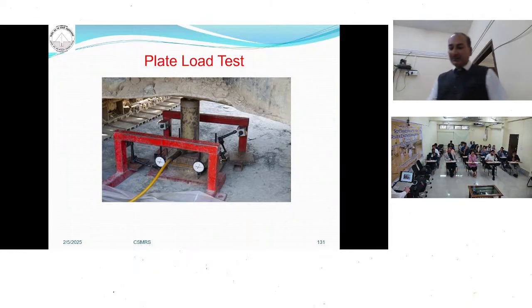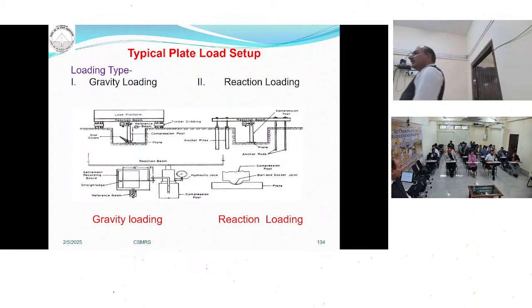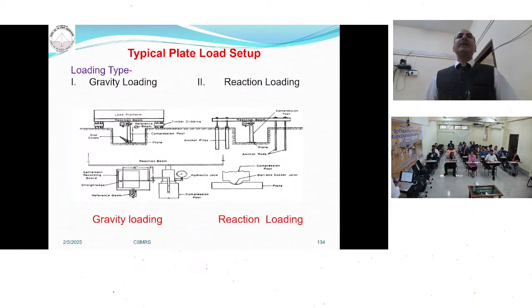Let me start right from the beginning. First of all, make a pit that has a size 5 times the dimension of the plate. So if we are using a 60 centimeter plate, then the size of the pit shall be 3 meter by 3 meter.